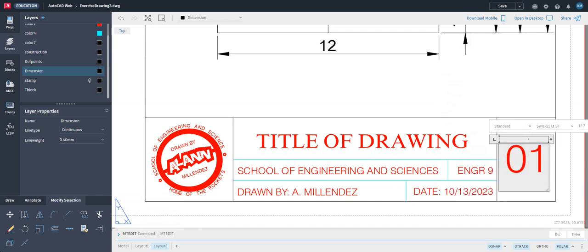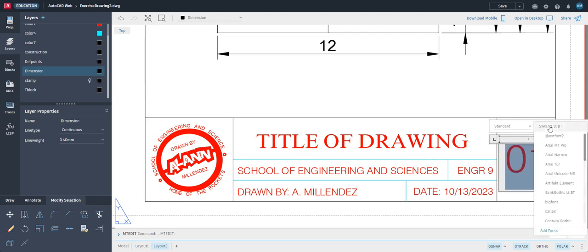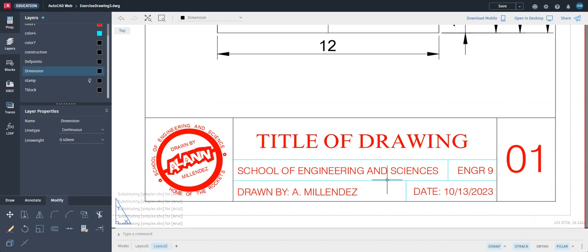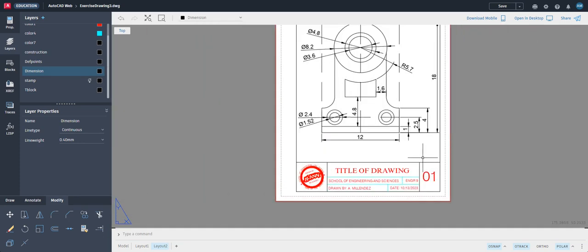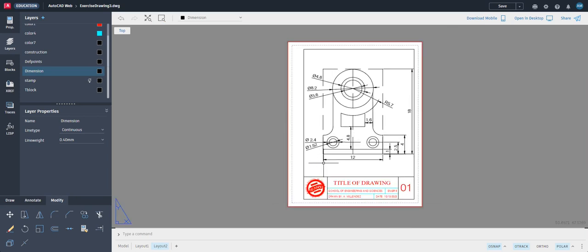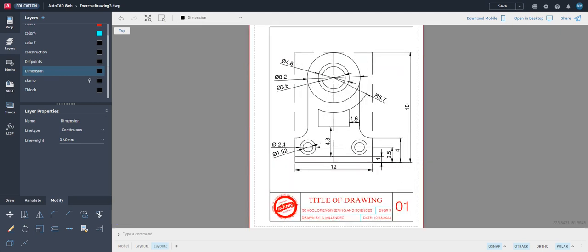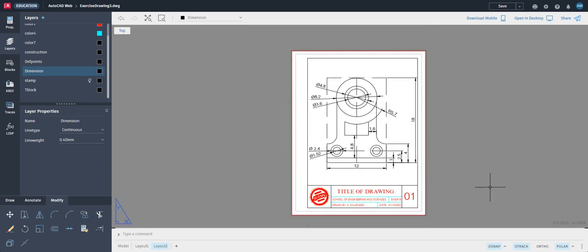Okay, and then this one I think is also Swiss. Double click. Yeah, and 1, 2, 3 is Swiss already. Click outside, and there you go. So now it's been updated. Unfortunately, this is a limited version of AutoCAD that we're using. This is AutoCAD for Education. We cannot create styles right now unless the drawing comes with a template.